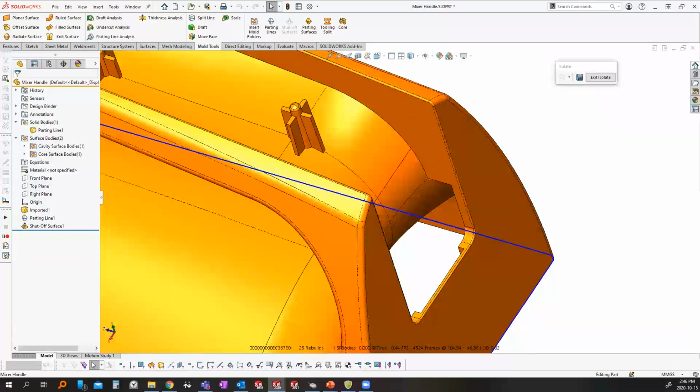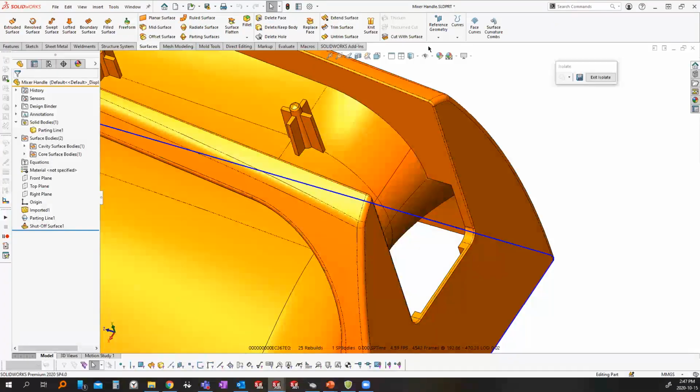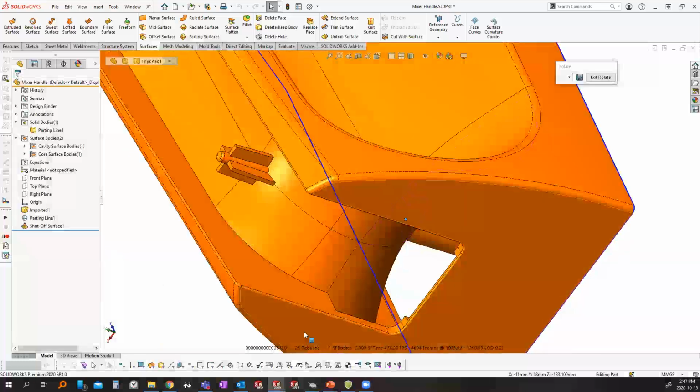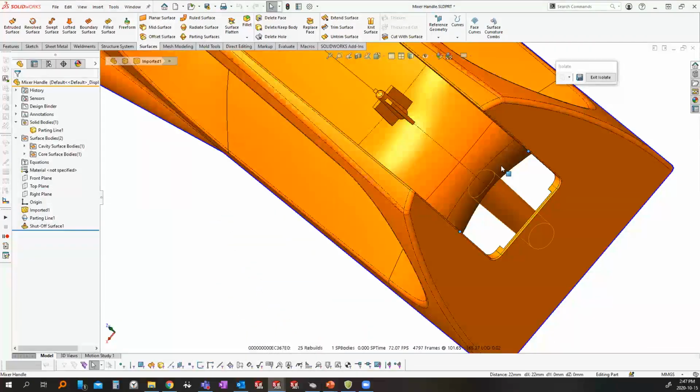You can imagine trying to develop a surface that goes kind of in this area. It's going to be interpolated for the most part. It's not going to be really well defined or, well, really what you want. So I'm going to divide it up into nice small chunks that are easy to develop my surfaces. I could do a 3D sketch to maybe say grab this edge going between these points here. Just point to point in a 3D sketch, that would work.